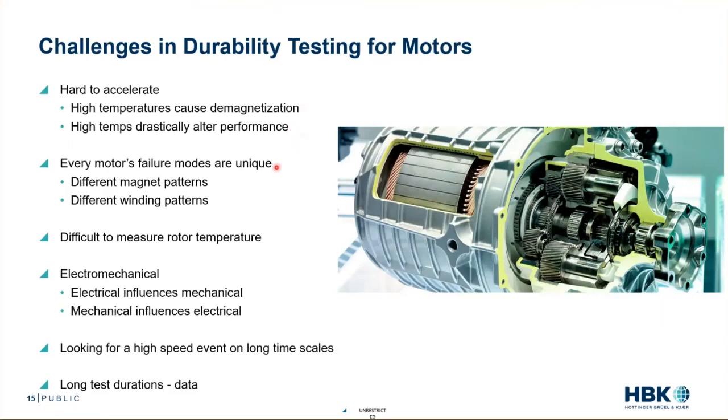Another challenge is, and I'm sure this translates to many other industries, but every motor's failure modes are a little unique. We have very different magnetic patterns. We have very different winding patterns. We have very different material properties from magnet to magnet even, or from winding to winding. So each one's a little bit of a unique butterfly. I don't think this is that different from traditional durability testing, but it is something to consider. We can't treat these as one size fits all.